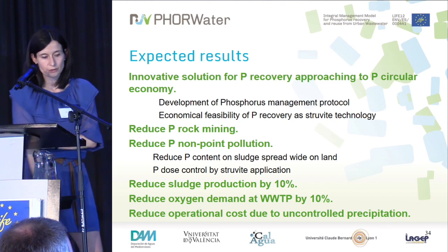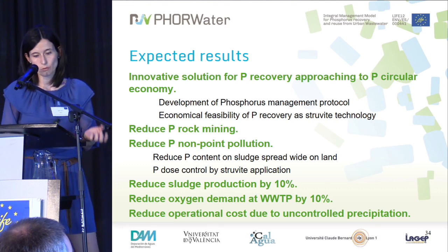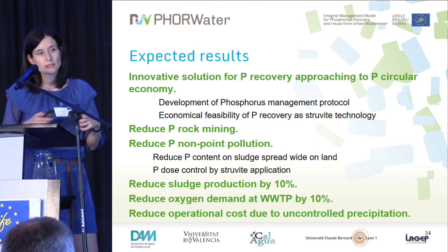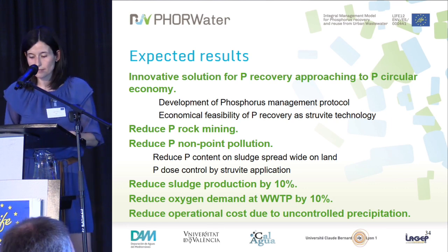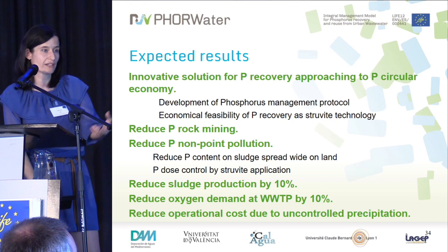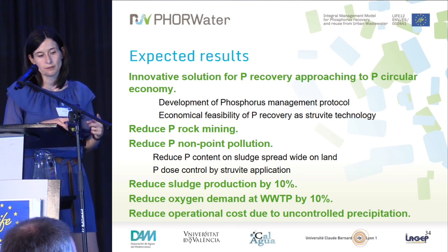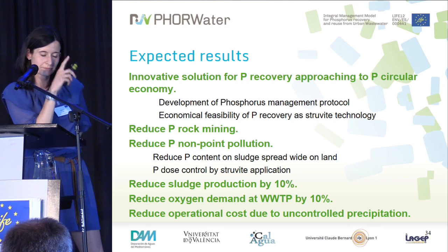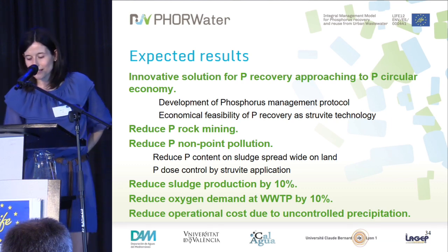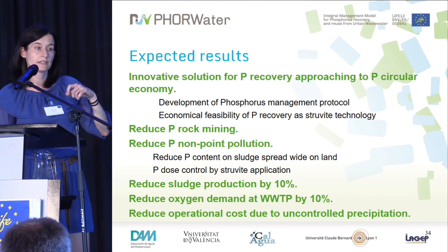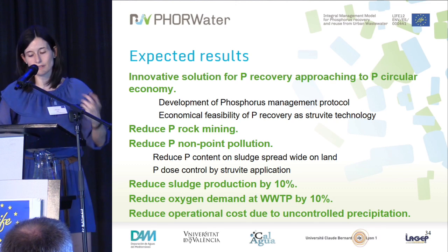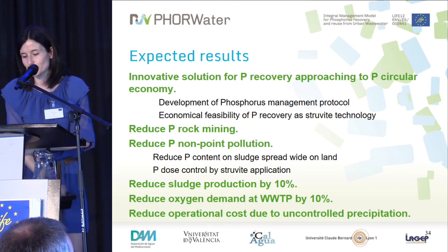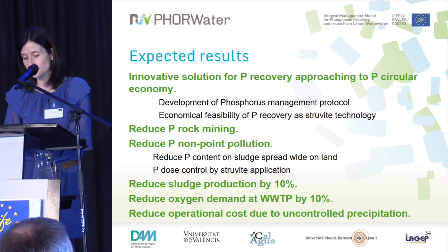We haven't done all those analyses yet, but what we have observed with the wastewater treatment plant data is that by improving the crystallization reactor, the energy consumption hasn't gone up. So we think that, I mean, we're using energy for the reactor, of course, but maybe the nitrogen that is not going back to the influent through the flows could be a reason for not observing an increase in the energy consumption. Also, it's a small pilot plant, so we don't know if with a bigger one we would observe any increase or decrease in the energy consumption.